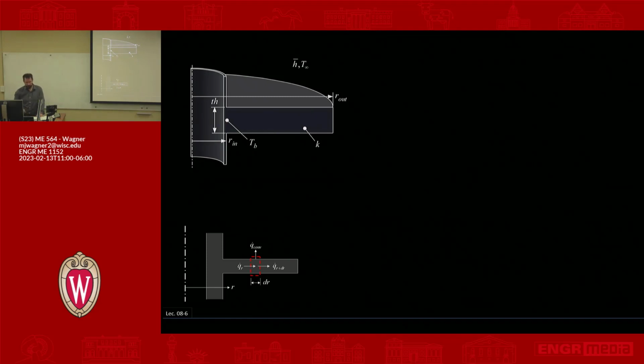First thing we want to do is decide whether an extended surface approximation is valid here. So we would first compute the Biot number. The Biot number is going to be the R conduction in the x direction. So I don't have coordinates here, so let's say this here is x, and this is y. Better make sure this is R, right? So we want to look at the conduction in the x direction and then compare that to convection, so R convection, or the resistance to the surroundings.